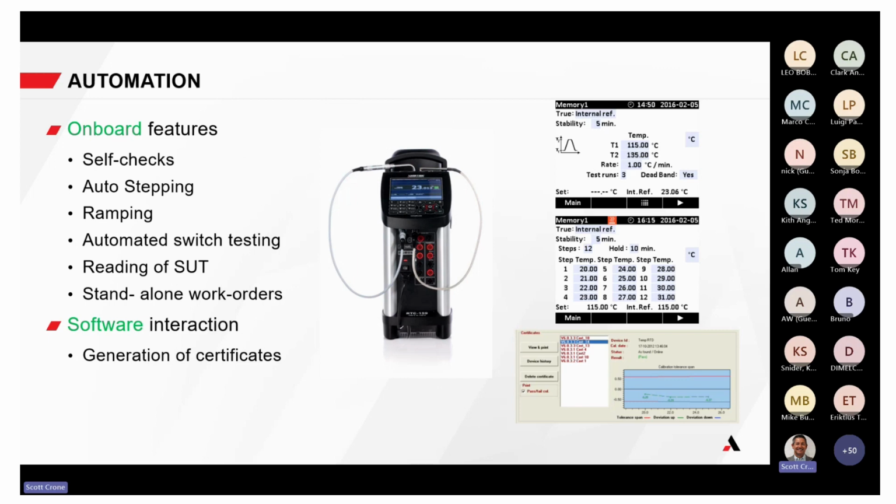But in this setup, you put the sensor in and then connect the leads to the dry block and let it run through the switch test. When it runs through the switch test, it captures those values all on its own. That is one of the biggest time-saving features used in industrial applications. That way the technician can be deployed doing something else.